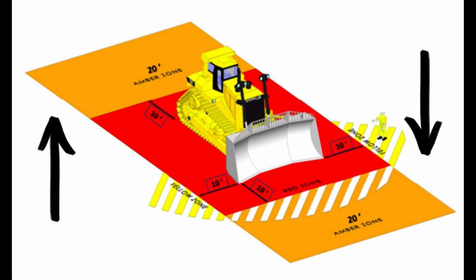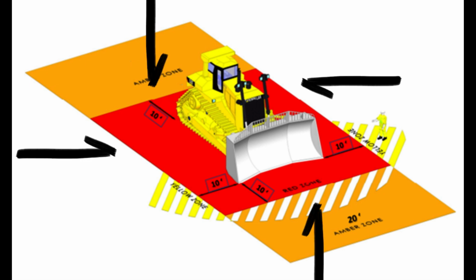Example, thumbs up, the dipper arm/hydraulics are grounded, the machine is immobilized using the safety lever and the engine is switched off. Red zone. A 10-foot zone where entry is prohibited unless the machine is completely isolated, the engine is switched off and a specific safe system of work is in place that prevents the machine being operated either inadvertently or deliberately.